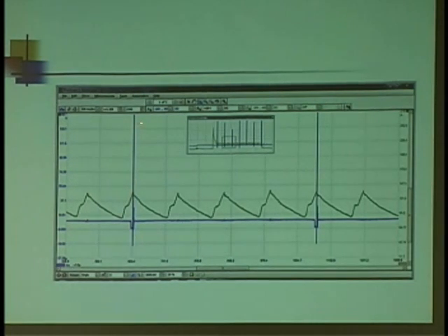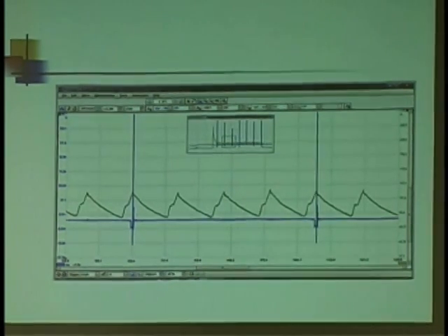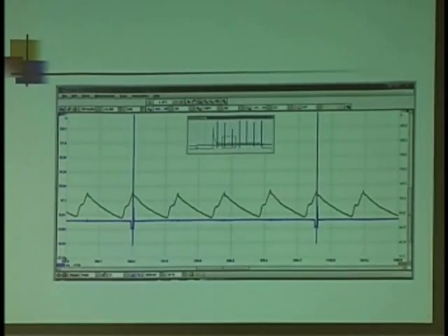When does this event occur? And that's a valid point. I mean, it looks like it's right dead on the money on the peak, okay? But if it were out of time, even a tooth, that would generally be at least 10, 15 degrees variance. So if it were out of time, I would expect to see it way off of that peak, left or right. Everybody with me?